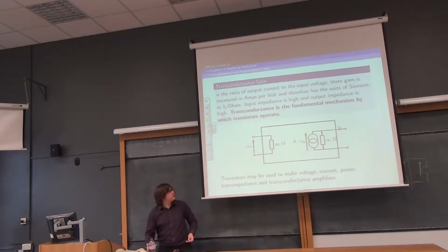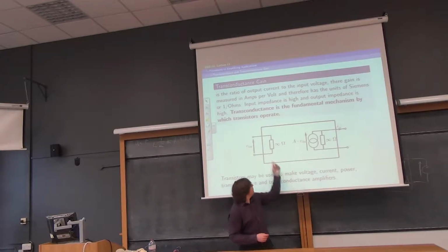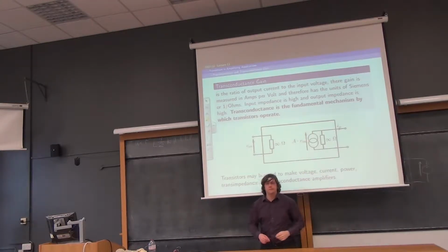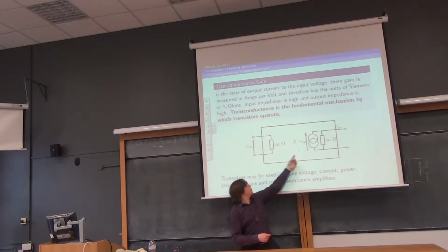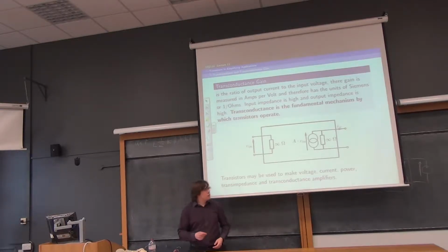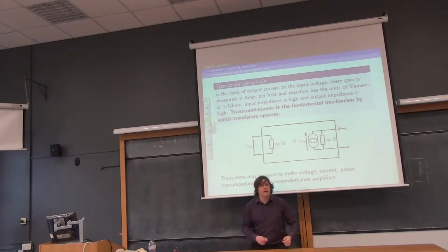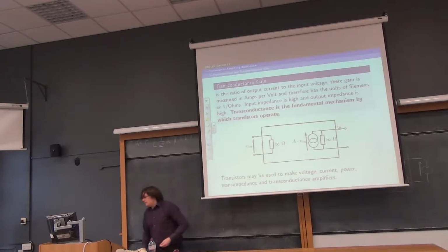The only thing that we're not doing here is we're not saying there are 3 terminals, we're saying there are 4. So this is a slightly more general amplifier than just a regular transistor. In fact, that node there and that node there are both the emitter. And then that's essentially the same as drawing that line between there and there, and then we've arrived at a transistor. Of course, a real transistor doesn't have infinite input impedance, and it doesn't have zero output impedance either. But we could say if we could manufacture a perfect device that was like a transistor, this is how we draw it out.